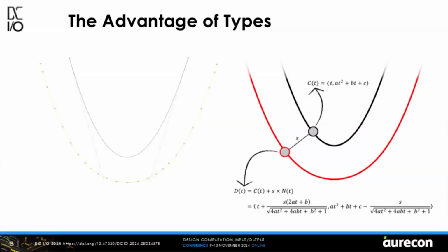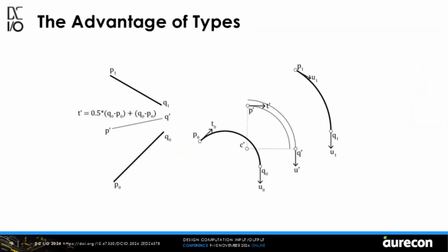The point being made here is that the only thing separating a civil modeling kernel and a non-civil modeling kernel is when something is an operation and when something is a geometric type. Geometry kernels are designed, and this type-operation dichotomy is one of the most foundational design decisions that can be made. They limit the user into particular ways of working, they streamline desirable workflows, and make certain workflows difficult or impossible. A very desirable behavior within the architecture, engineering, construction industries is that types can be maintained for drawing and dimensioning as they are interpolated.